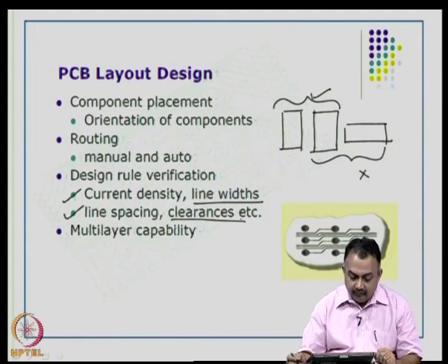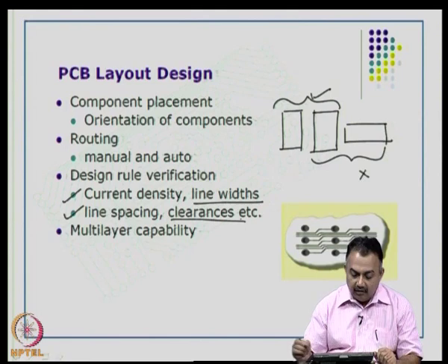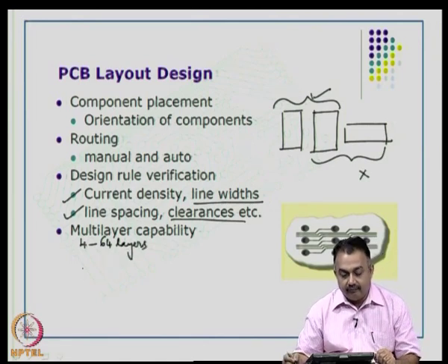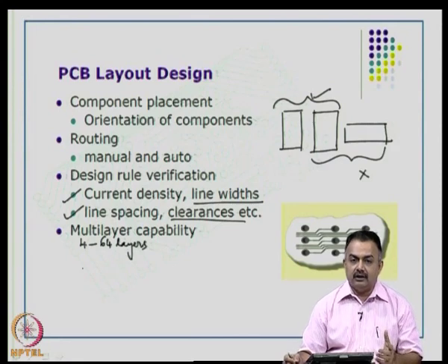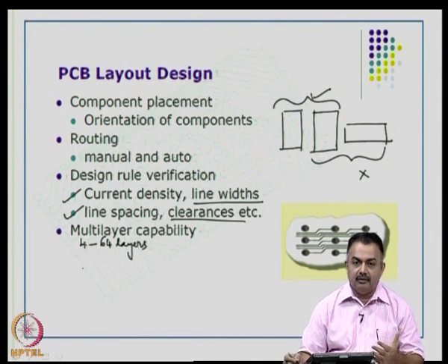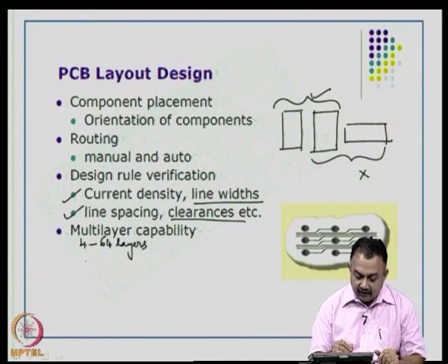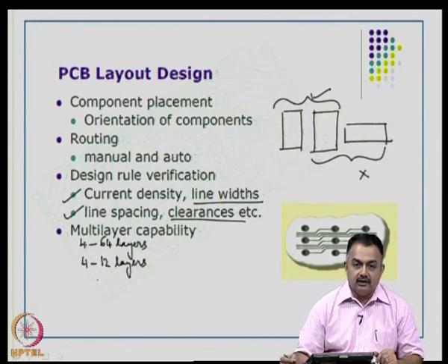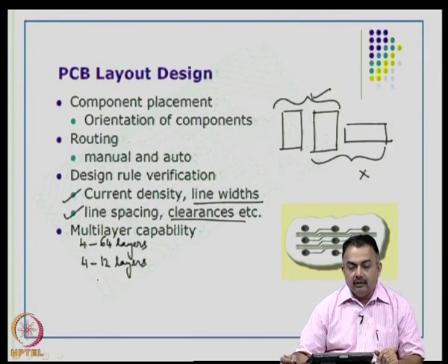and so on. And your layout should also be able to generate multi-layer boards, right from 4 layers to, let us say today even 64 layer boards have been successfully fabricated. But obviously, in a commercial board or in a handheld device or a communication product or a desktop motherboard, you will not require this many layers. Typically, the handling capacity will be around 4 to 12 layers. Higher layer count is usually for more strategic applications. So, multi-layer capability should be possible using your layout.